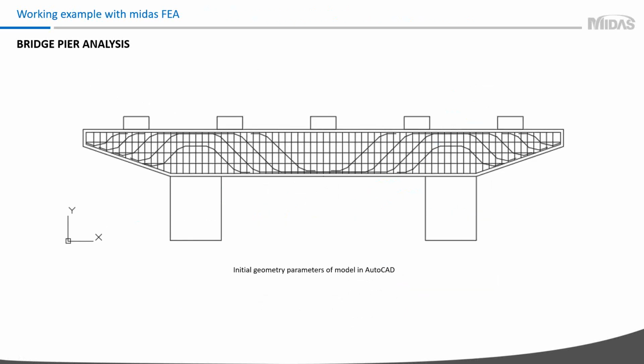The easiest way to begin modeling is to start with AutoCAD. Almost everyone who works with structural design works with AutoCAD as well, and this tool is quite convenient for creating initial parameters of the model. In AutoCAD, you can draw a contour of your cap. You can draw reinforcement, pads, columns, just using simple lines, and then you can save this model in a DXF file.